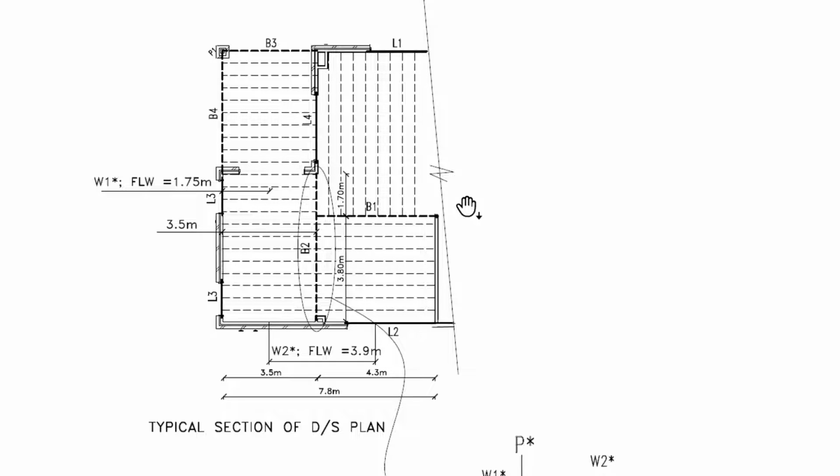Then we have the beam members such as B1, B2, B3 and B4. Beams are generally positioned in the floor space. Sometimes beams that are also positioned in a bulkhead, we can call that a beam rather than a lintel. Lintels are generally nominated for members over a window or a door head.